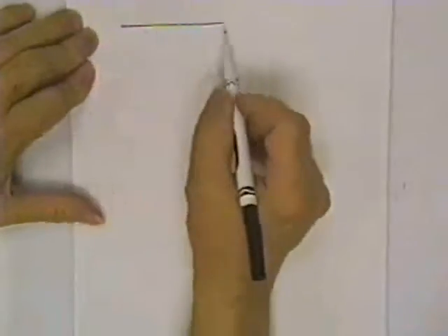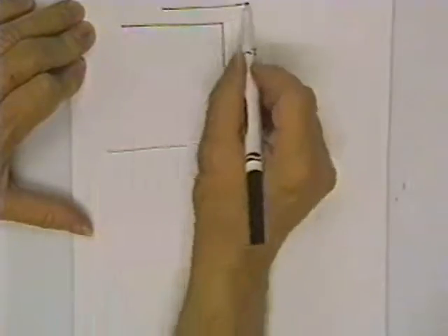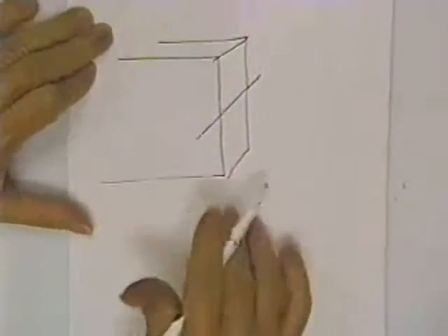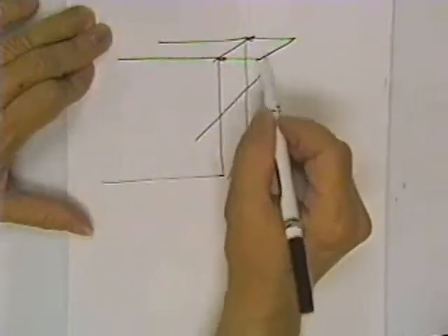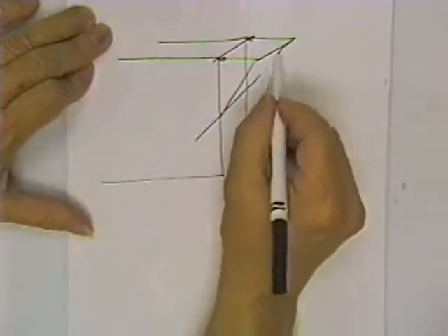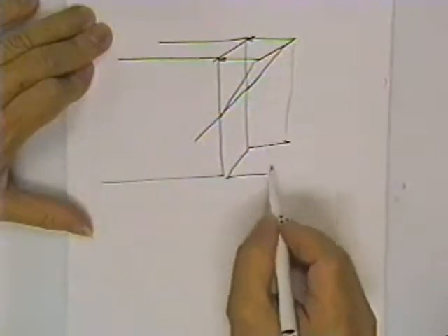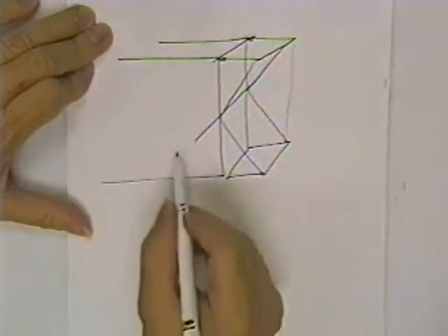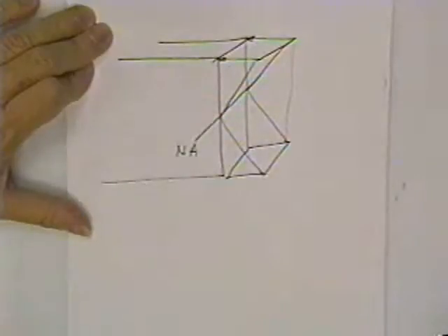Showed you in a beam, let's just say it's a rectangular beam, that that beam will normally have compressive stresses on one side of the beam, and they'll have tension stresses on the other side of the beam, and they are distributed linearly from the neutral axis. They are maximum on the outside fiber. They're zero at the neutral axis.